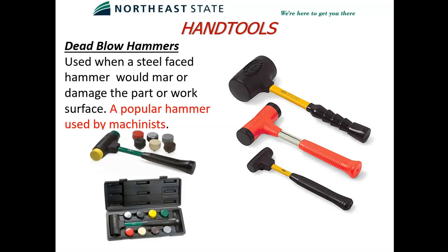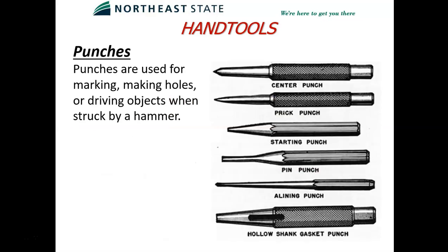That's what it means. And then the other ones there have interchangeable faces for different degrees of softness of rubber. This is a popular hammer used by machinists because they don't mar the work surface. They don't leave dent marks and wave marks and things.